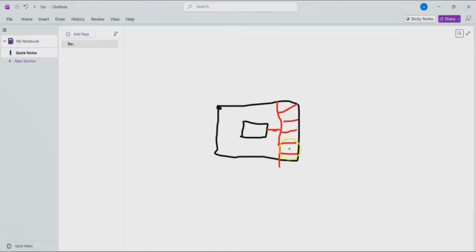So if you are taking a look at this distance in the x direction, then this will be the critical section. Then if you are taking a look at this part in the y direction, at the distance of d, which is the effective depth of the footing, this whole area is going to be the critical section.